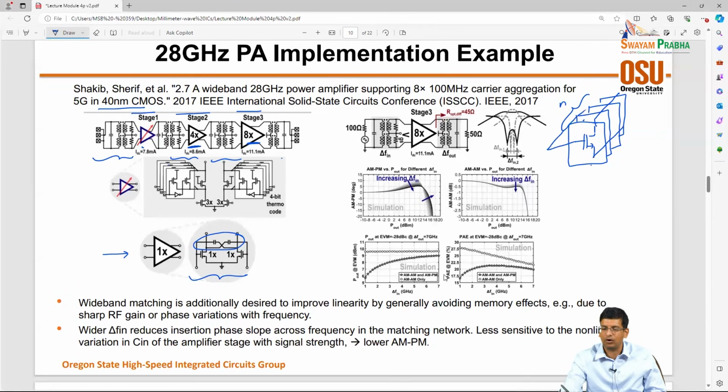We have not considered those wiring parasitics. So then there's another round of iteration where we start wiring these devices together and then do another load pull set in order to see whether we are still in the right output power range, right. And these load pulls can be done across V bias, in order to find out which is the right V bias to get a certain EVM or to get a certain P out, PAE, right.